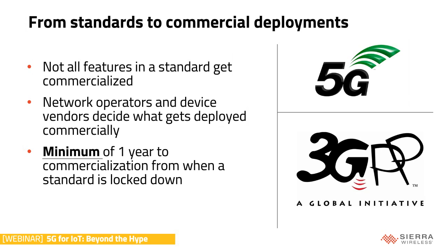The Standard Development Organization, which is defining 5G, is 3GPP. I mentioned that in my introduction. But not all these features that 3GPP puts into the specification do get commercialized. For example, 3GPP defined an LTE device probably 3 years ago, which in theory can support 25 gigabits per second. But this device in practice would need 8 antennas, 32 by 20 megahertz of carrier aggregation, which is obviously not commercially practical today. Today, commercial LTE devices are really supporting maximum data rates closer to a gigabit per second versus 25 gigabits per second. So you can see that there's quite a big difference sometimes between what's in the standard versus what is commercialized.